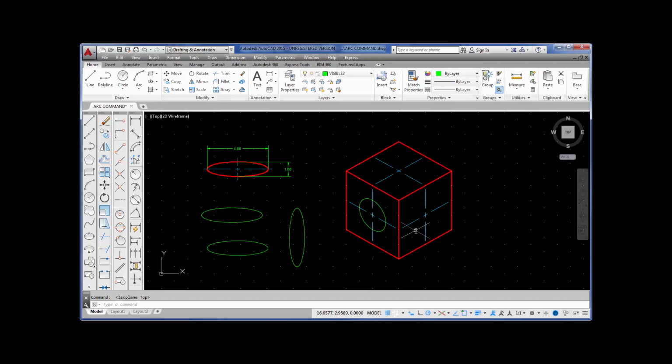So now I'm going to try for an isoplane right ellipse. I'm going to select the ellipse button, get the center again. Note it. Beautiful. I just made a mistake. Now, in my script, I do have this mistake to show you, but I did it without even looking at the script. What I forgot to do was type in I for iso circle.